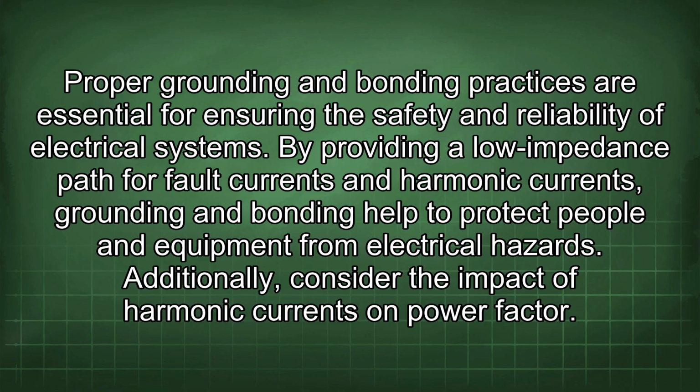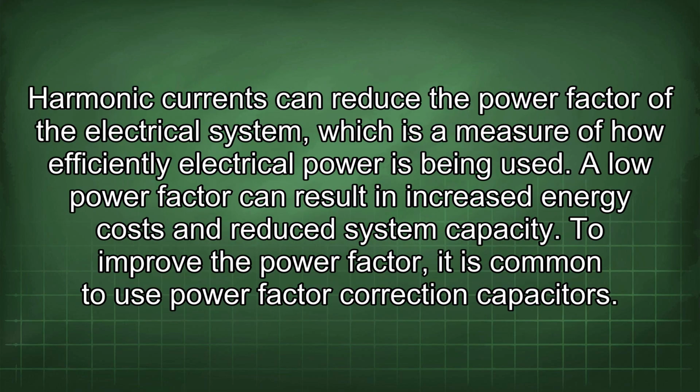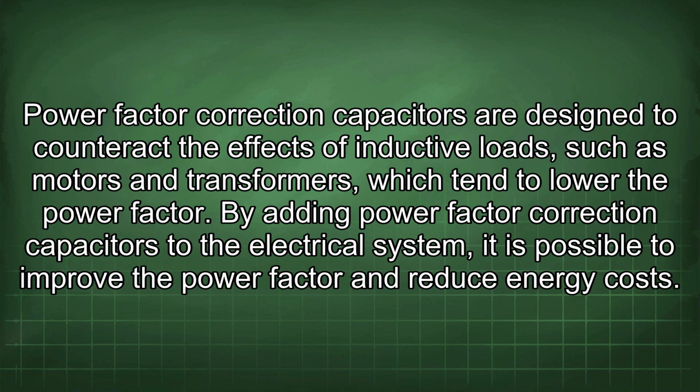Additionally, consider the impact of harmonic currents on power factor. Harmonic currents can reduce the power factor of the electrical system, which is a measure of how efficiently electrical power is being used. A low power factor can result in increased energy costs and reduced system capacity. To improve the power factor, it is common to use power factor correction capacitors. Power factor correction capacitors are designed to counteract the effects of inductive loads, such as motors and transformers, which tend to lower the power factor.